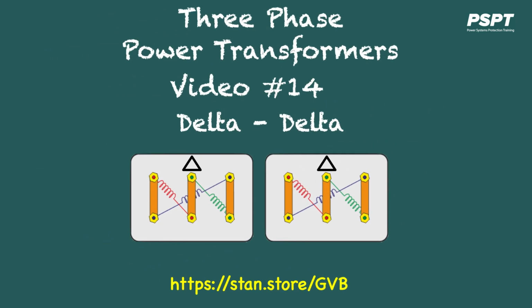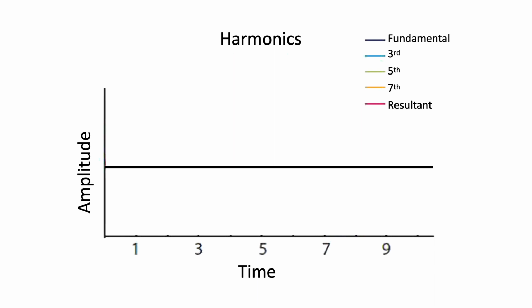Before having a closer look at this type of transformer, we need to understand what third harmonics and tertiary windings are. Harmonic voltages and currents in an electrical power system are the result of non-linear electric loads. Harmonic frequencies in the power grid are a frequent cause of power quality problems. These in turn could result in an increased heating of the equipment and conductors, or the misfiring in variable speed drives and torque pulsation in motors.